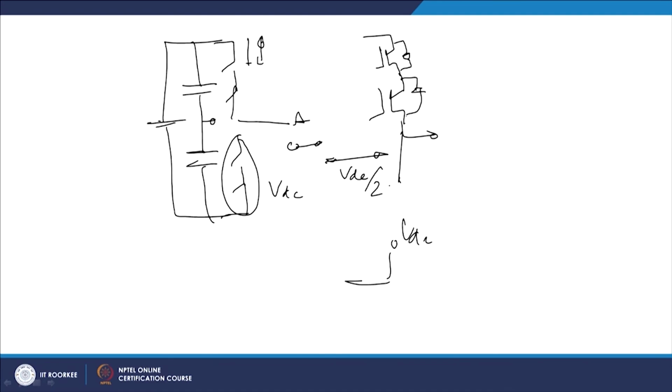Now, in the next configuration, this is position 1, and in the same way when you come to position 2, what happens? This switch gets shorted. And it has to be bidirectional. For this reason, we require a switch that is bidirectional in nature. So, we can realize a 4th quadrant operation of the switches. So here you require an anti-parallel diode.